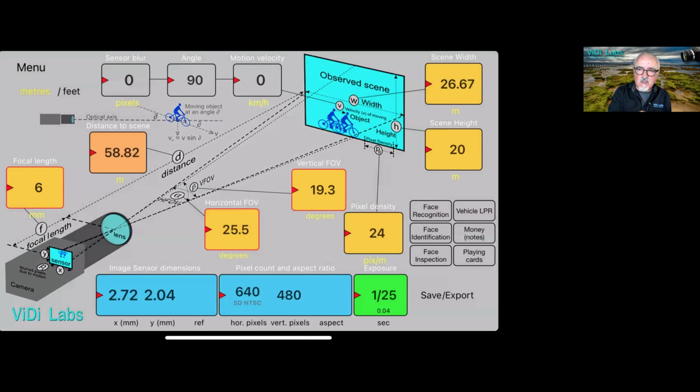In this case the sensor itself will be bigger because it's got more pixels, times 0.017. How much bigger? Let's calculate that. So I have 640 times 0.017, because we said that those manufacturers don't give you the sensor dimensions like we know it in the visible IP CCTV.